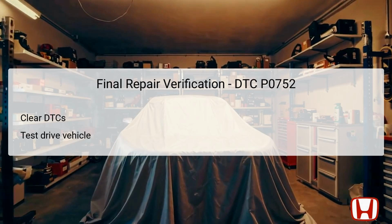The test drive should mimic typical driving conditions, allowing the technician to validate that the vehicle shifts smoothly and responds accurately to gear changes. This step is essential to ensure that no residual issues remain and that the repair has successfully addressed the root cause of the DTC.